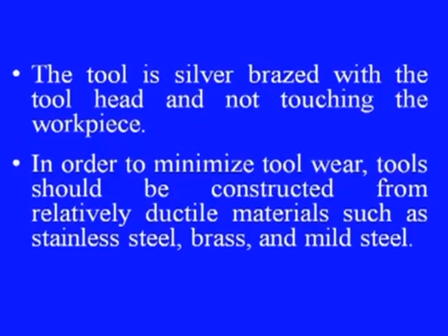A unique benefit of this type of micro USM is to realize a parallel production of many identical simple features. Like gang drilling, we can have a number of holes drilled simultaneously using a number of tiny micro tools. The tool is generally silver brazed with the tool head and not touching the workpiece.